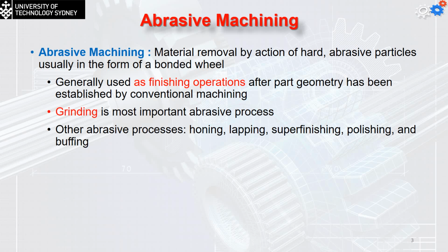How can we do the super finishing, or the finishing of the surface, to have it bright and very fine? We do a process called the grinding process. Abrasive machining is a type of grinding process. It removes the material now as a very fine layer, and the form of the material to be removed is not going to be a chip. It's going to be somehow a powder. Okay, so we remove material as a powder, a very fine layer, to have a very good surface finishing.